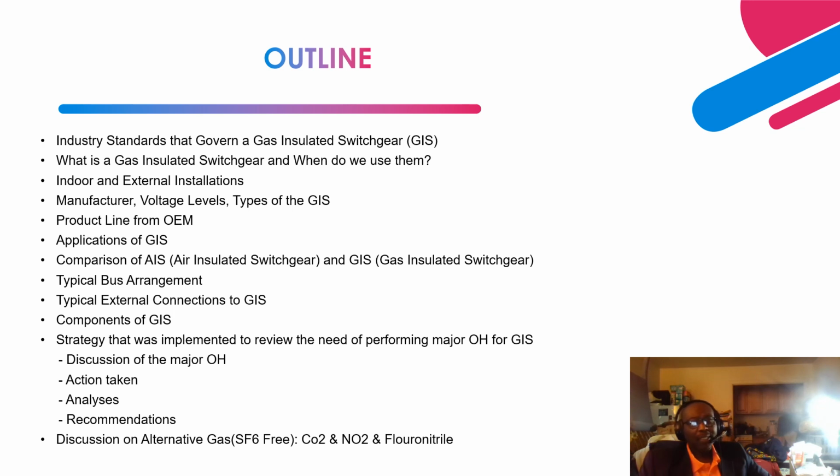And basically, for a typical connection to an air insulated substation, we use typical air to SF6 bushings. That is exchange of an interface of air to SF6, and that is integrated to an air substation.